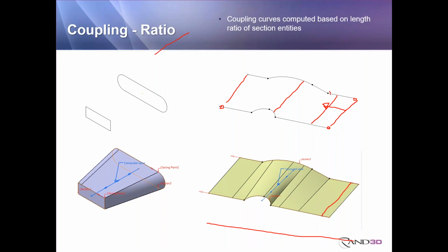Now what will happen is it starts to find the percent and starts to connect across. When it gets to this one corner right here, this is where the line comes together with the arc. So it's then going to internally break the surface. So let's say this is like 15% along here. The computer's then going to connect to the 15% point over here. It's now going to continue along further. Again, it runs into this next break, so it's going to divide this piece up and then find the corresponding percent point over here. Same thing's going to happen when it gets into this break right here. It goes across, so it creates the shape just basically based on percent distance to connect them together.